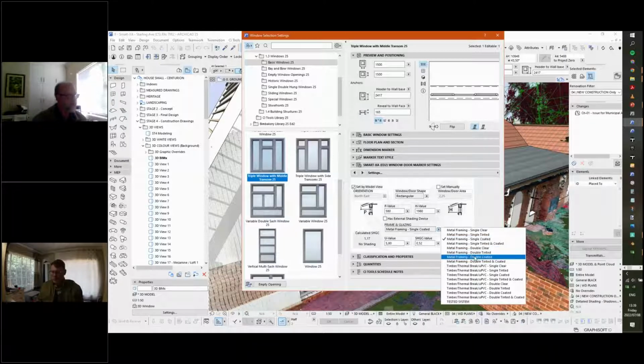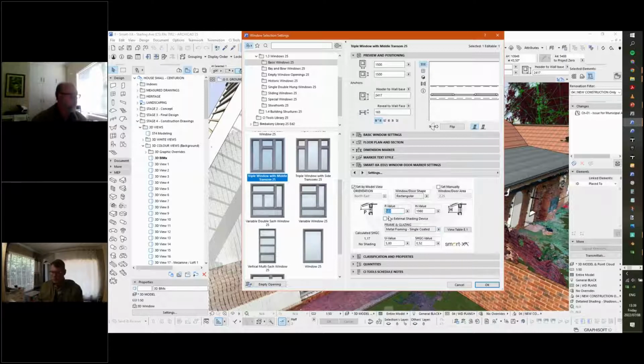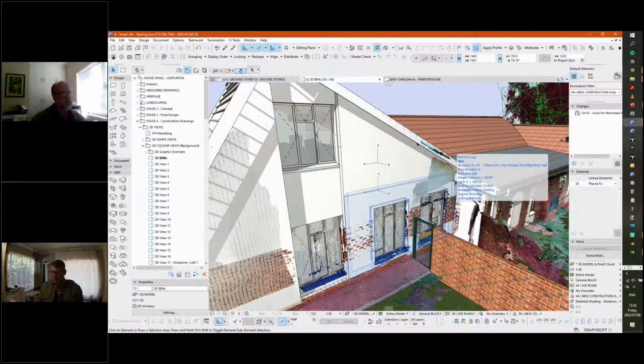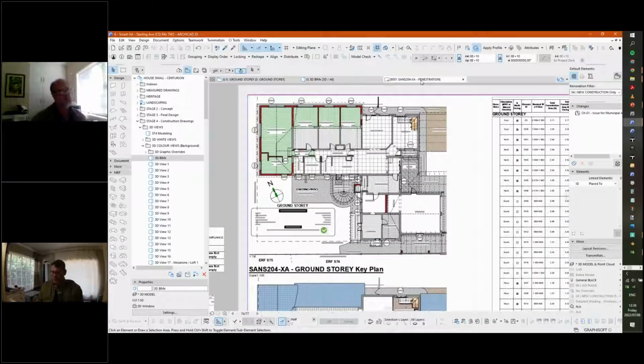You designate the frame and glazing combination from the table, and after physically measuring in the section, the P and H values, you enter them here, and that basically takes care of the settings and your interaction with the model for the analysis then to happen. In addition to that, you'll place zones and for area calculation basis, and that's basically in short, the setup, and Archicad will do this for you, right?